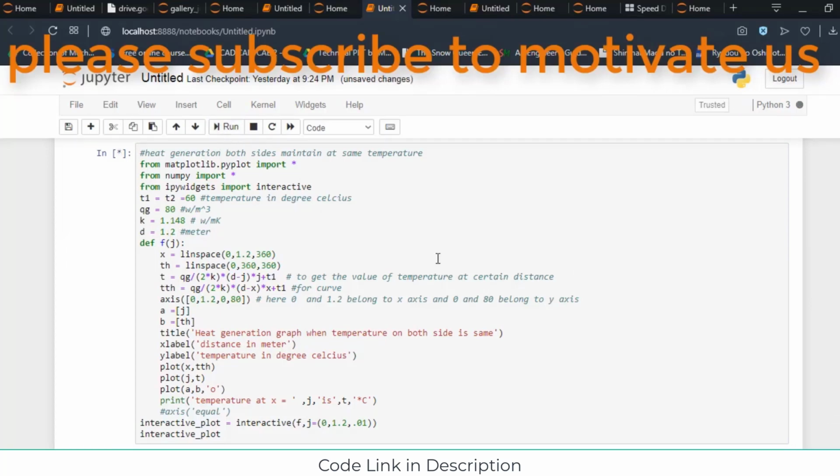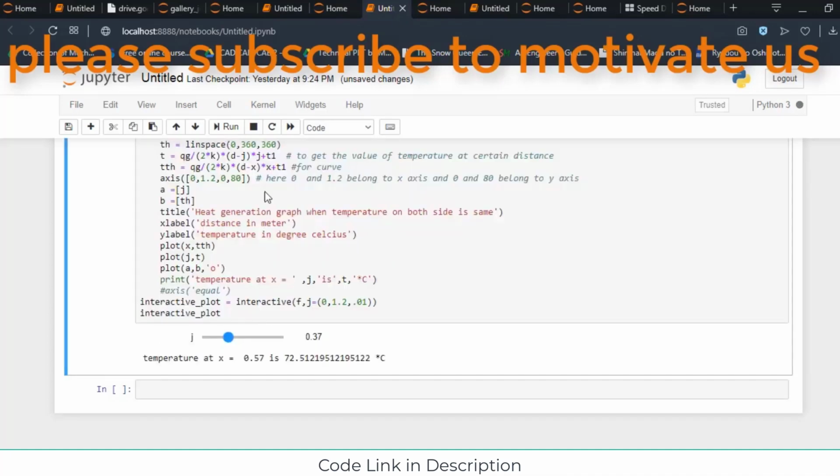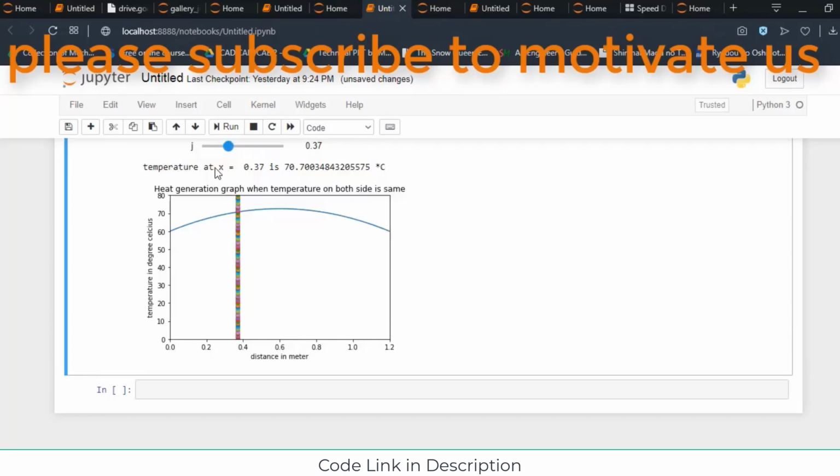So here first I run the code so you can see what's going on. As you can see, the thickness of the slab is 0 to 1.2 meter. When I decrease the value, I see that at 0.37 meter from the left side, my temperature is 70.7 degrees Celsius. But at distance 0.6, I see the temperature is 72.54 degrees Celsius. So the temperature is increasing at the center because of the heat generation.